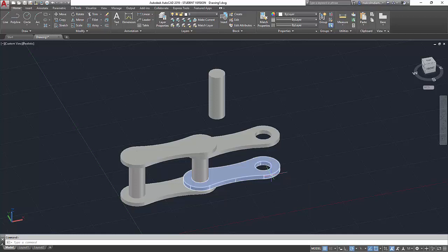Hard, huh? The quickest way is not to use a third pin. The quickest way is to use the existing pin and pick it up by one of these 3 points. I could draw a little sacrificial line from here, going downwards a quarter of an inch, and then move the pin, so grab the pin and grab the bottom of the line so that it is actually grabbed a quarter of an inch down. Don't copy the line, just the pin, but you can use that line that you put downwards in the Z to pick it up by, but that's a little bit convoluted. So I'll show you the other way.